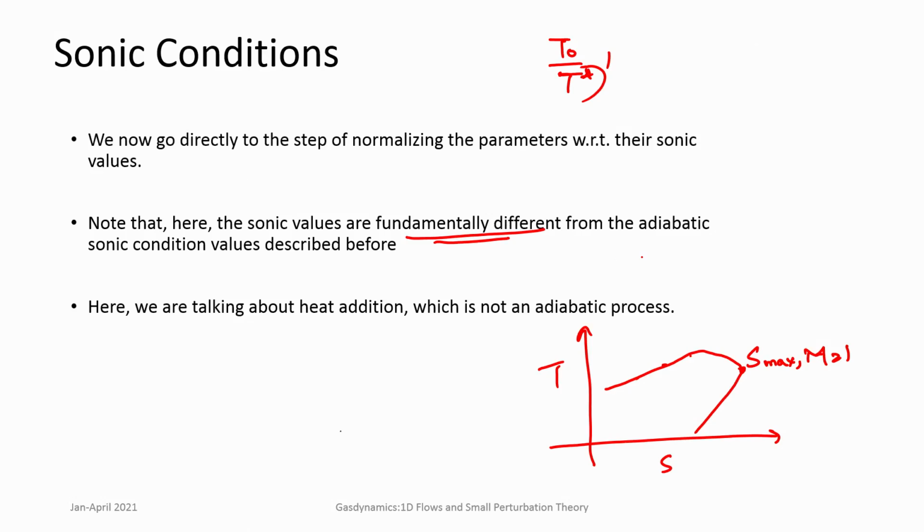But what you should understand here is that for a given Rayleigh curve or for a given Rayleigh flow, which implies that G is a constant, it is a steady 1D flow, the mass flux will be constant, and P plus rho v square equal to constant.